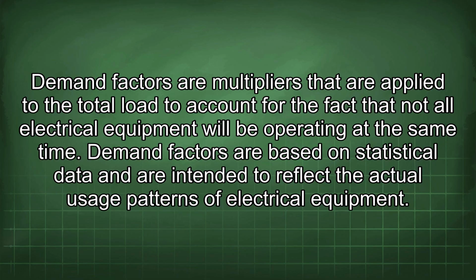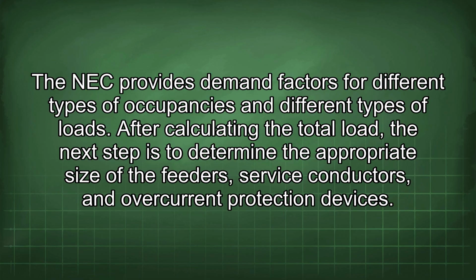Demand factors are multipliers that are applied to the total load to account for the fact that not all electrical equipment will be operating at the same time. Demand factors are based on statistical data and are intended to reflect the actual usage patterns of electrical equipment. The NEC provides demand factors for different types of occupancies and different types of loads.